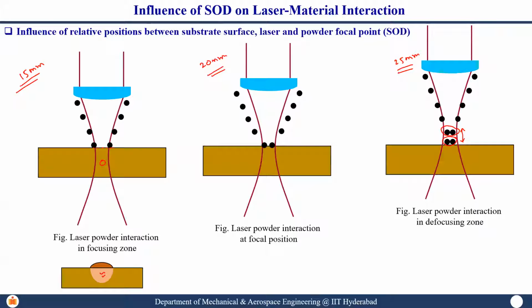If you see here, the lens locations are not at the same height. So what we do is, let us say I displace my laser head by 5 mm in the Z plus direction. Then I will move my lens down by 5 mm so that your focal point will always be at the same location. The nozzle which we designed in 2012 in my MTech had that provision, and now if you buy from any company, they have introduced this by default. So you can move the lens within your cladding head. Oh, okay. So one is moving up, one is coming down.